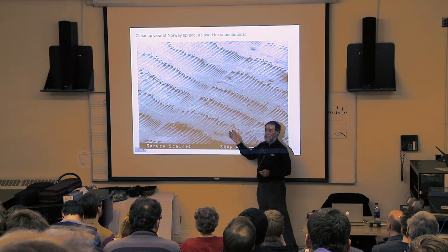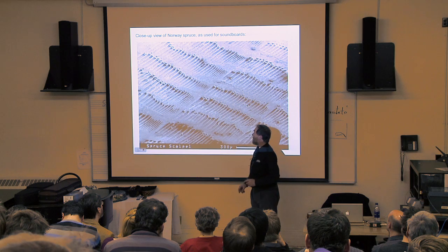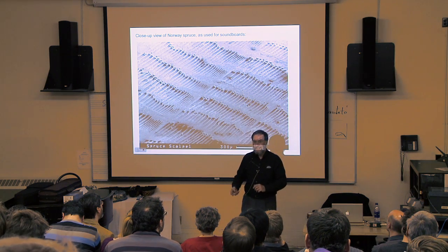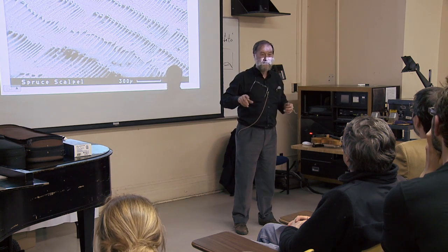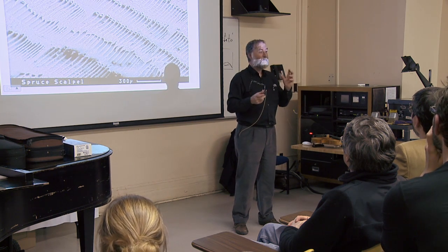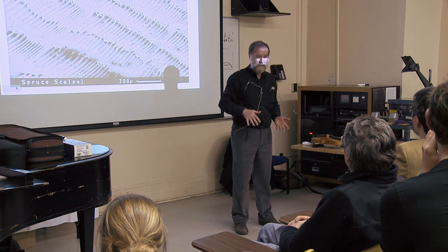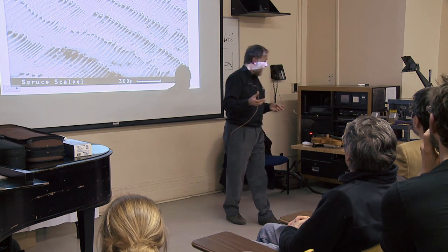We can't quite do this yet. We can do it on a bigger scale. Every time you're on an aeroplane, you're standing on something with structure a bit like this. In the middle of aeroplane floor panels is a sort of aluminium honeycomb. If I was at home, I'd have a piece with me, but you have to imagine aluminium honeycomb in a sandwich panel with metal plates, so you don't see it, it's inside. And it gives you a very light, stiff floor, which is what you need for aeroplanes.